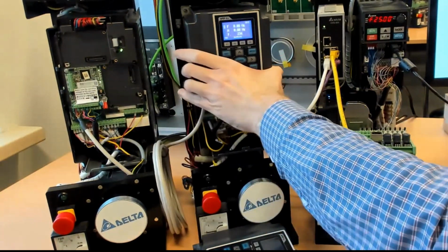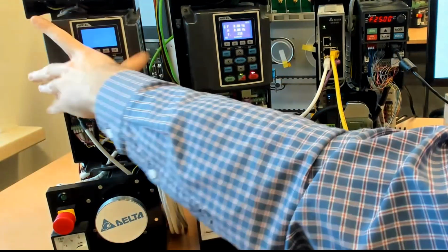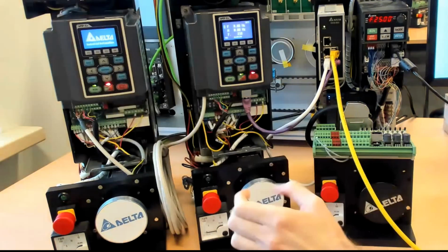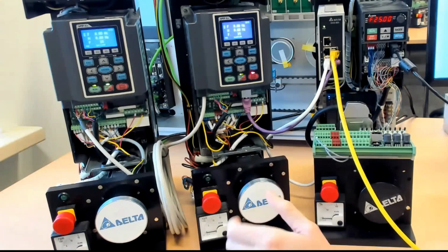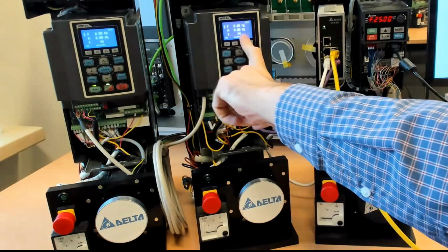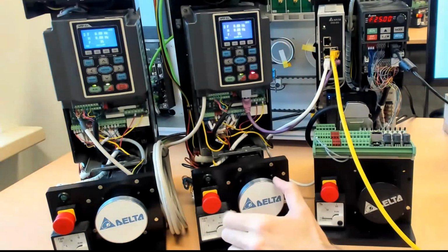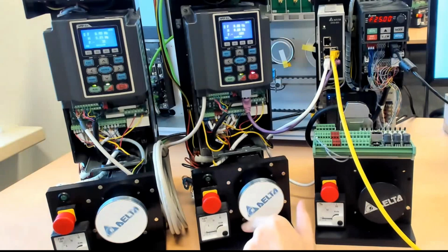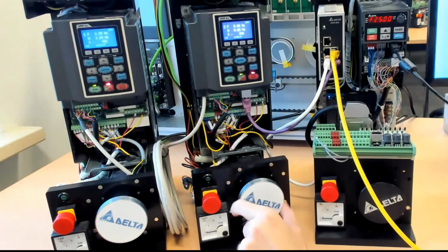Currently the follower drive is set to try to follow the position of the master. It can also try to follow the speed of the master, but since it's a C2000, it's more performant to follow the exact position. So you can monitor here the actual motor position. Here it is 34 and also 34 or 35, and then I can move it. The drive more or less follows it accurately.